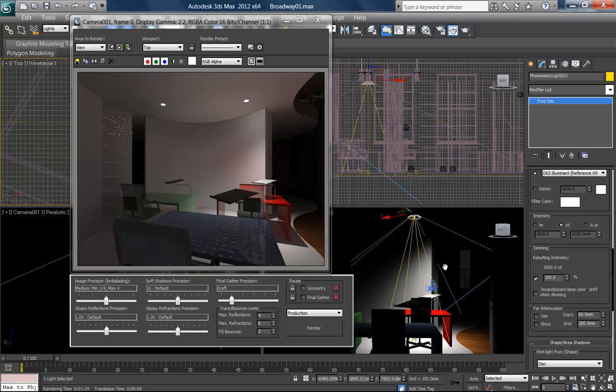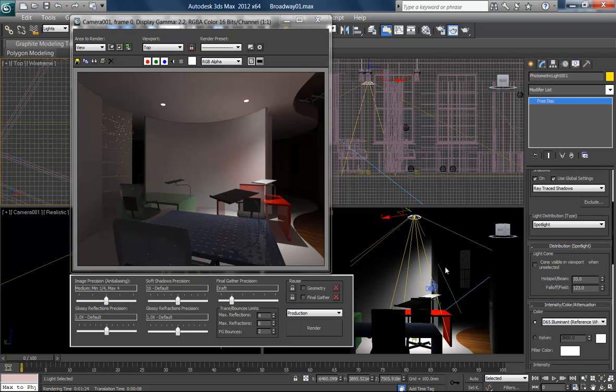If you want to type them in here, just turn the option down below off for the percentage, and then you can just type in directly whatever you use. Otherwise you just type in a percentage. So that's 100% of 3,000, and if you want 1,500, you make it 50. I don't mind working in percentages, but direct units are good as well. And if you don't know any of these units, candelas aren't a bad one because they're meant to be equal to one candle. So in theory, this light is as bright as 3,000 candles.